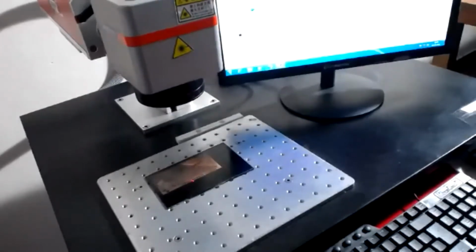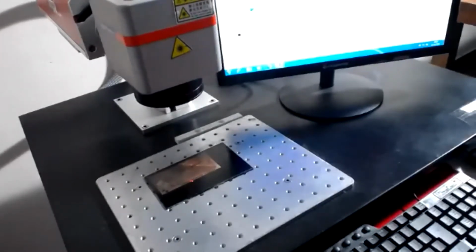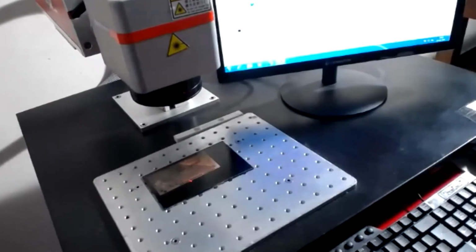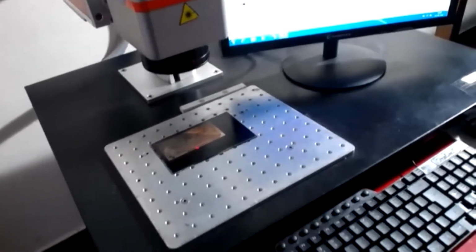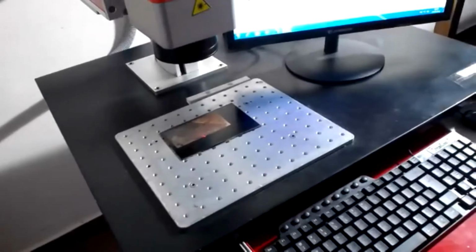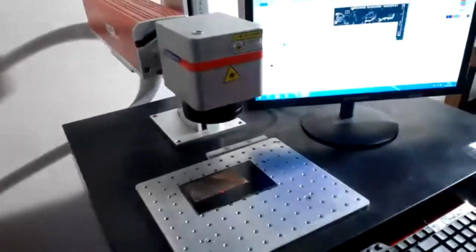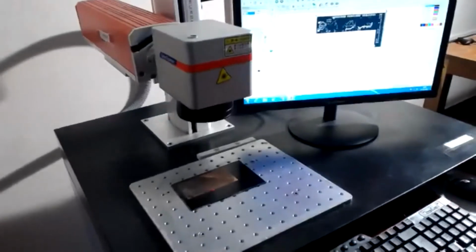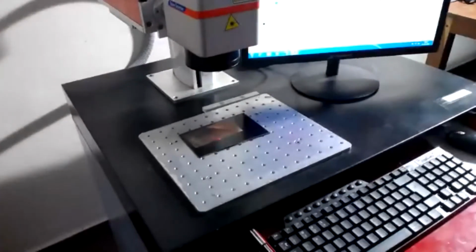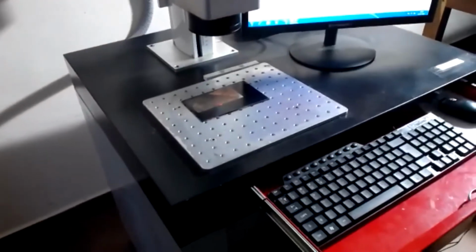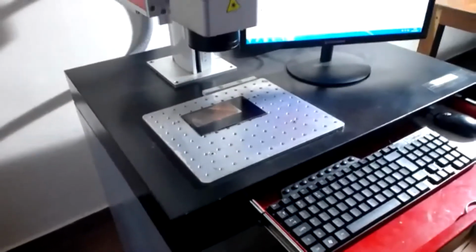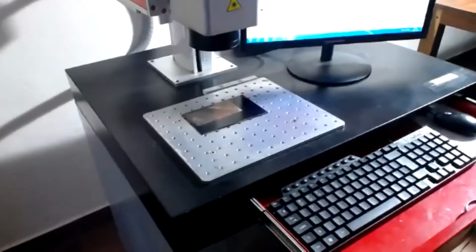The only thing is, I'm not limited for the vias. The size of the vias is not limited. So with this laser, I can even go for 0.3 mm vias. The trace clearance also, I hope many of you are aware of it. The trace width should be 0.3 mm, and the distance between adjacent traces should be 0.3 mm. And there are some more measures you should be very careful about when you design this circuit.